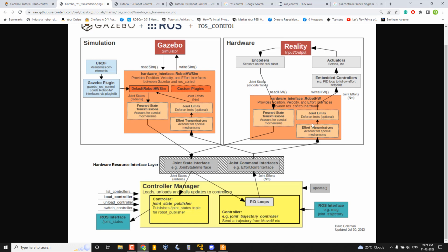You can do both. One approach is that the hardware interface can talk to the driver layer through topics. Whenever the hardware interface gets the control commands, it can directly write to the actuator through topics, or maybe you can use some serial communication to the embedded controller. So here, this is the command going to the motor.